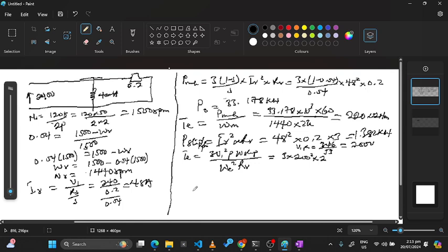Then this omega slip, remember omega slip is equal to S omega E. So then we are going to have times S times omega E, which is 2 pi times 50, all divided by 2 pi times 50 squared, then RR. The square here will cancel whatever we have here.